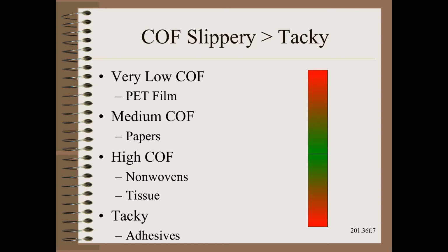COF and tackiness affect web handling a bunch, and winding a big bunch. Would you be surprised to find that either extreme can be challenging? At the low end, we have path control issues in web handling and telescoping type 2 in winding. At the high end, where webs are tacky, we will likely have great trouble in winding rolls that are round, and they will almost certainly vibrate if wound at higher speeds.